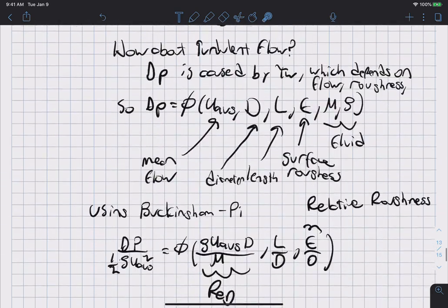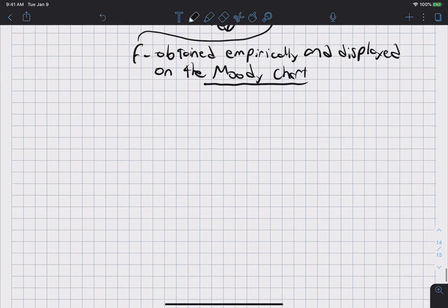And so there is another way to compute the Darcy friction factor. So how is f turbulence calculated? Because that Moody chart had some very nice smooth curves, and it is an empirical chart, and certainly they didn't do an infinite number of experiments to fully characterize that chart. Well, a guy by the name of Colebrook actually took a lot of empirical data and did a curve fit to it.